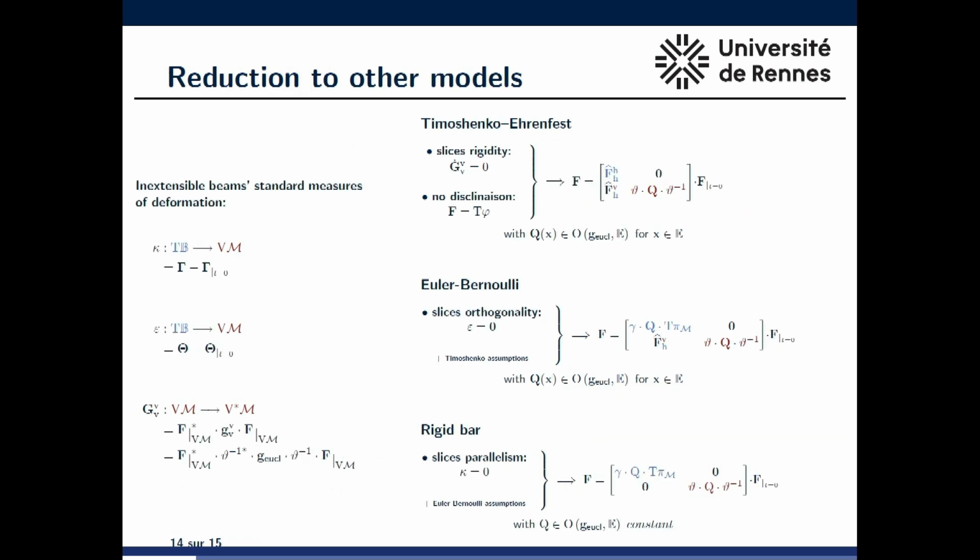In this case, I've tried to reduce to the usual beam model, which has no defects, so it probably doesn't have any torsion. But in general, it can have torsion and can have curvature also if we do not force F to be the gradient. And there has been some example by the previous thesis where there is an explicit construction, an explicit transformation, where there is torsion and there is a curvature tensor that is not null.